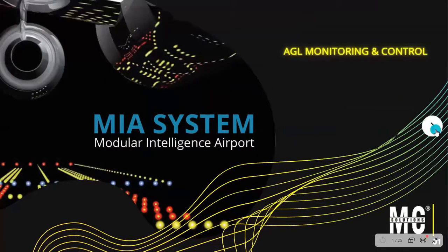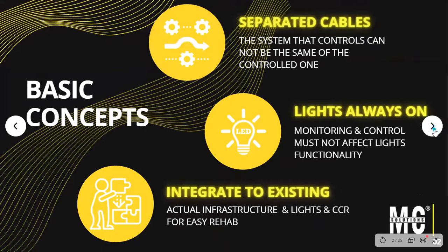Okay, so our AGL monitoring and control system. First of all, as I told you before, we will start from the basic concept. Just think about a fire alarm system, and you will never power the fire alarm system on the same cable that gives the alarm data. So starting from this basic concept, we have developed the monitoring system on separate cables because the system that controls cannot be the same as the controlled one.